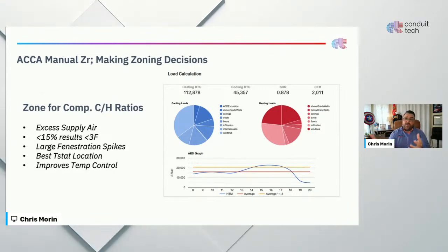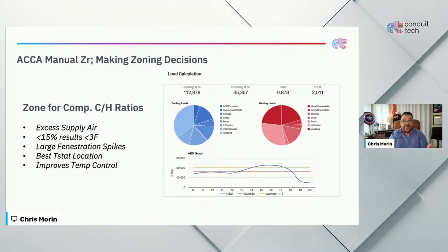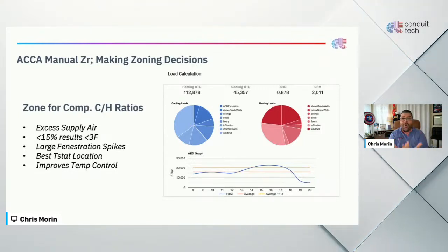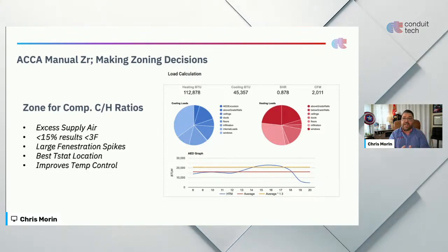Obviously, you have to make sure you're going to put the thermostat into a living area, right? Not just a hallway. I see this all the time, and we'll talk about things that you don't do in a second here. I'll reiterate this. But if you have a central return in a hallway, and that's where you put the thermostat, we don't live in the hallway. So we've got to stop doing that, right?